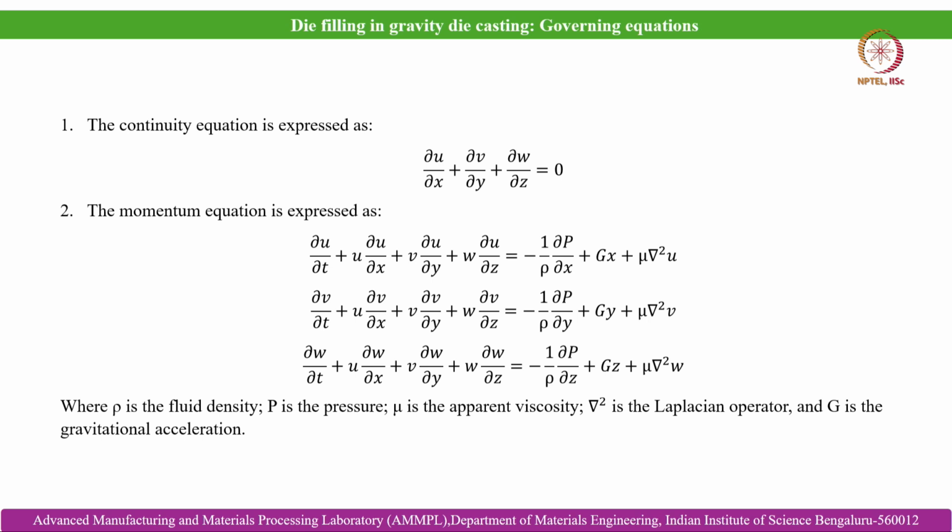So, you can see basically how we do that. We need to solve the conservation equations to simulate and quantify the flow behavior of the liquid melt within the die casting. Since we are talking about gravity casting, this is applied to a low superheat casting. So, we are considering the flow in the superheated melt state, although the superheat is low. That is why during filling there is no mass exchange, that means no phase transformation is happening, which is what is assumed here.